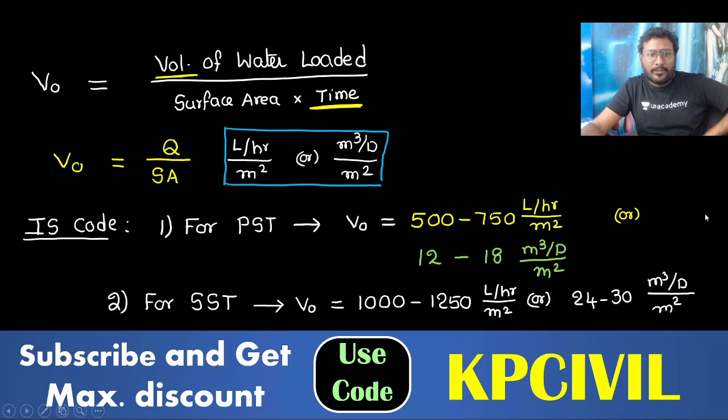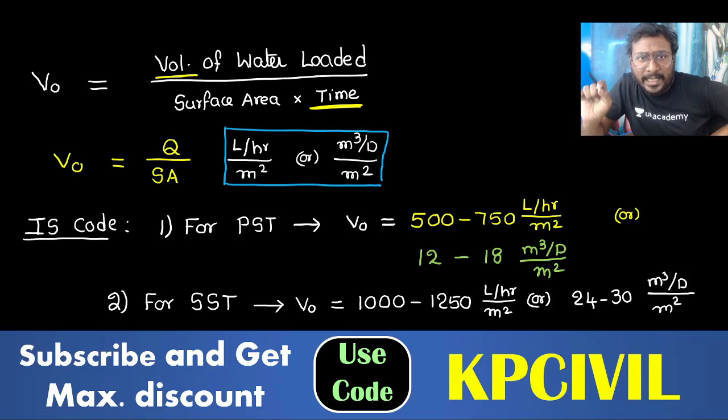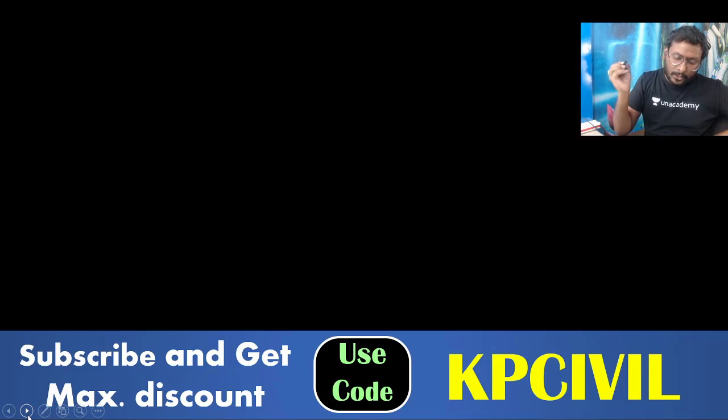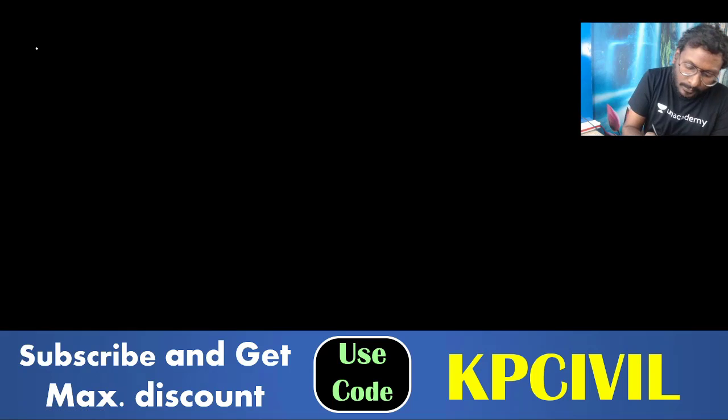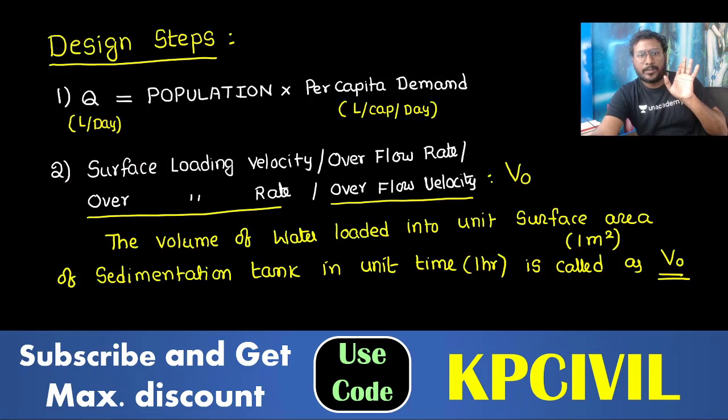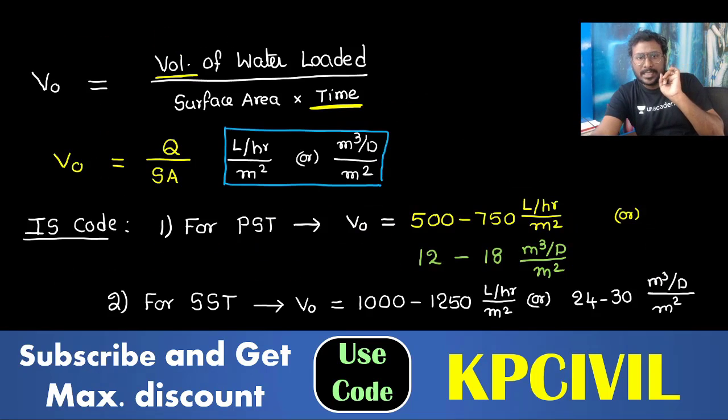So what is the meaning of this? You are selecting any one value; you are not calculating V0. So you know V0 and you know the discharge. First step, estimate the discharge. Second step, select the V0 value from the IS code.